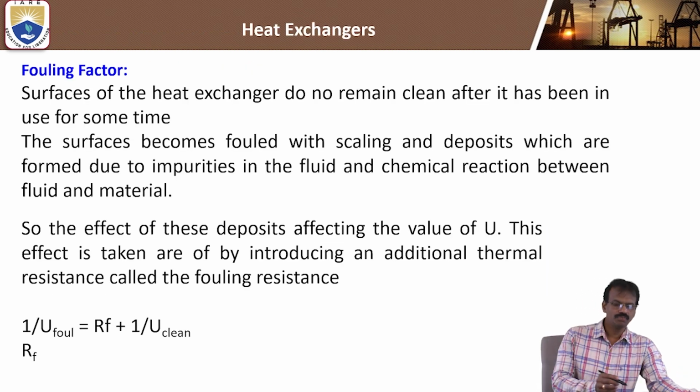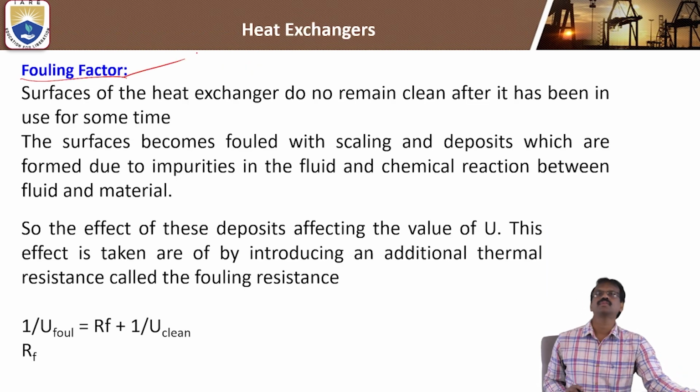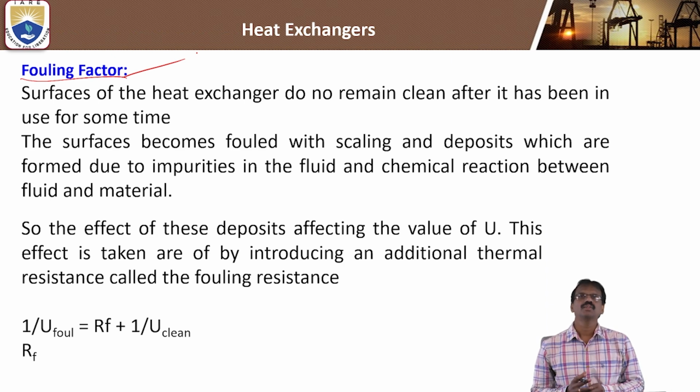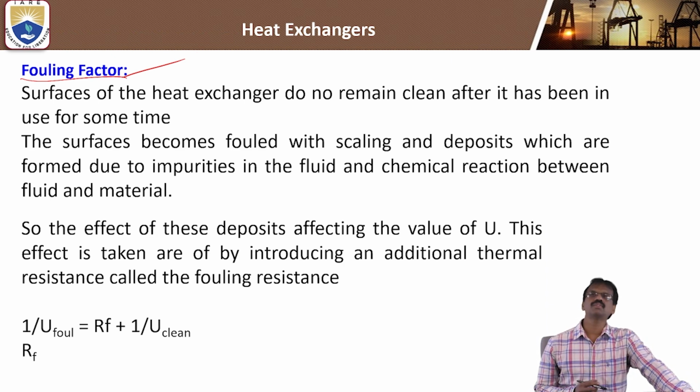Next, we will see the fouling factor. What is the fouling factor? Generally, the surfaces of heat exchangers do not remain clean, because when the fluid is flowing on that surface, a chemical reaction takes place between the fluid impurities and the surface of the tubes.